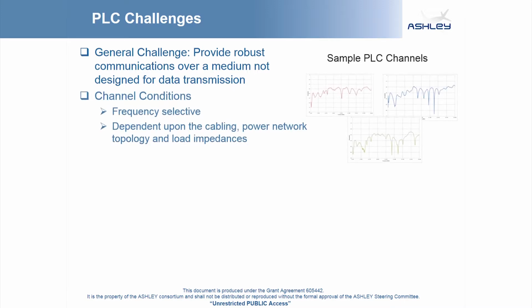The PLC channel will be highly frequency selective due to reflections occurring at impedance discontinuities. The sample PLC channels shown here show the distinct notches or regions of high attenuation due to these reflections. As the channel is also dependent upon the topology and load conditions, the channel will vary from location to location, even within a single network.